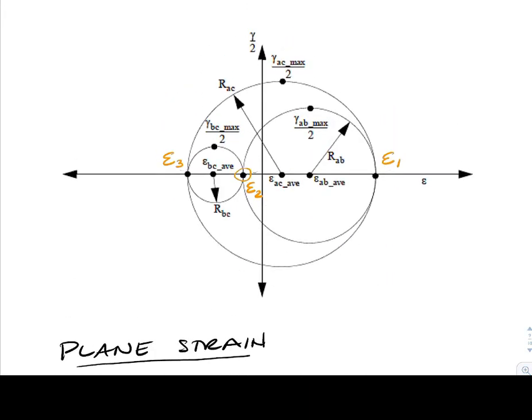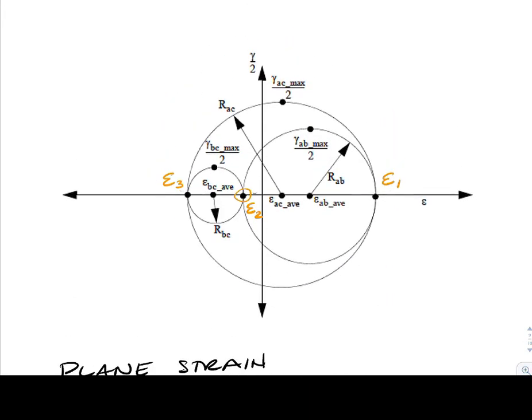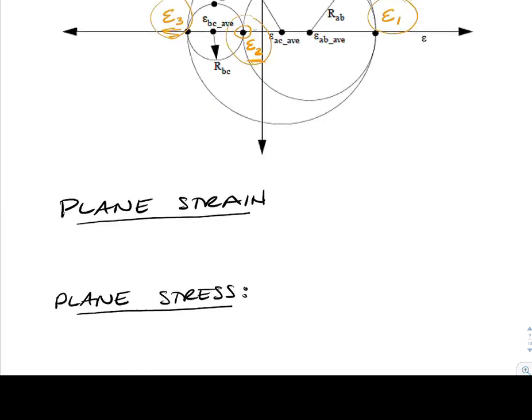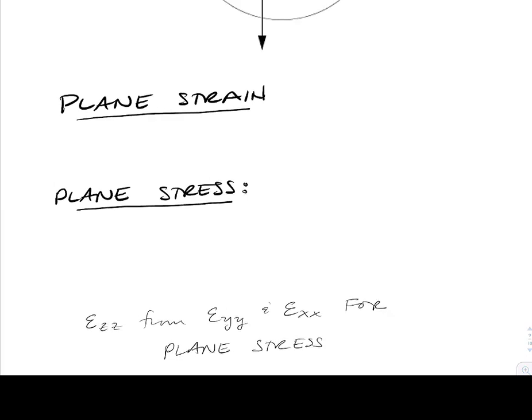Here it would be in 3D, dealing with the 3 principal strains. So once we know our Mohr circle in 3 dimensions, then we can deal with all of our 3 principal strains. Those principal strains relate to principal stresses, and we've seen those relationships in 3D Hooke's law. So a couple problem types.